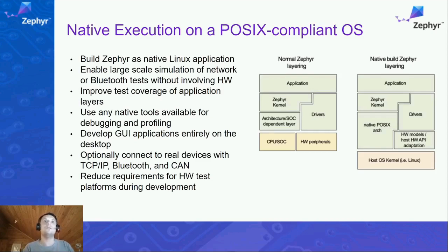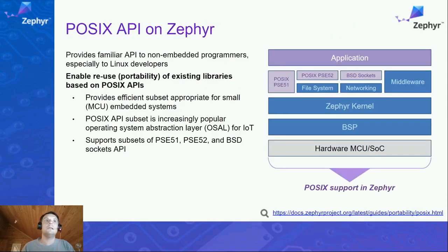So it's very useful, and this is something that has seen a lot of adoption, and we're seeing now contributors adding simulators for SPI, for GPIO, for I2C, so that you can even build applications that communicate with external hardware, obviously virtually, using the simulators. So this is another area that's under very active development in Zephyr if you're interested.